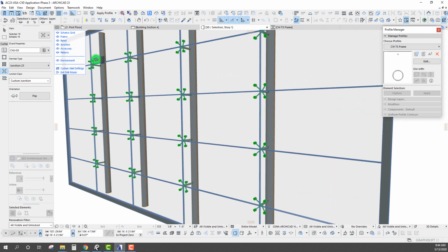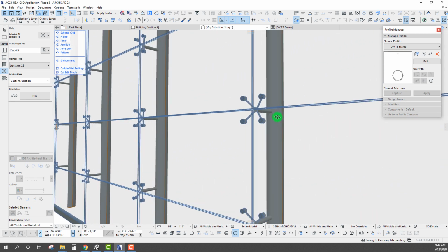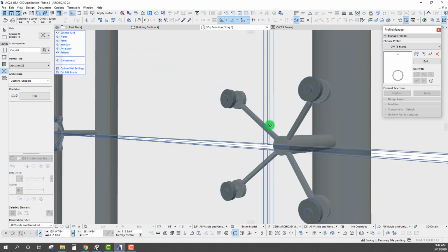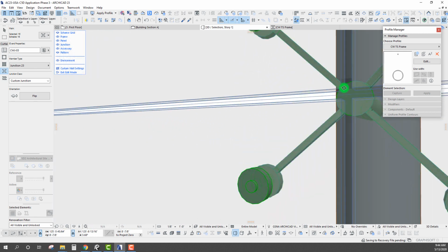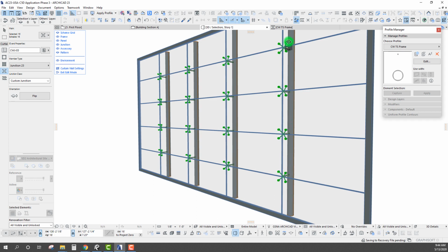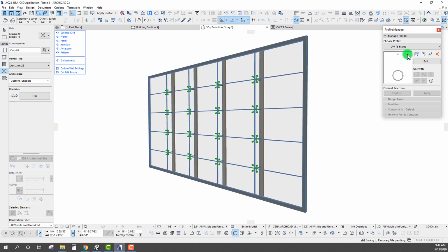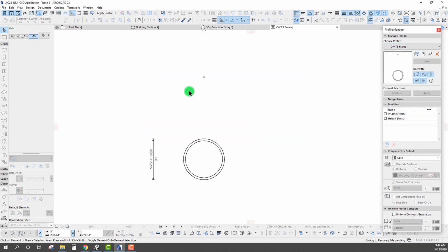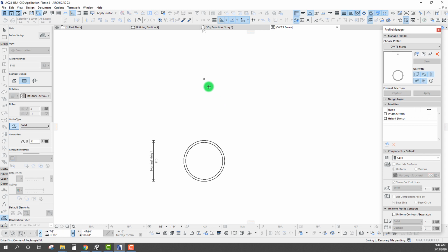And okay, so I'd say to add just a little bit more realism to this, instead of having these actual gaps here, let's create a little bit of a sealant strip there. And we can actually do that directly from within our curtain wall tube steel frame profile. So we'll go in here, and once again we have a 1 inch thick glass panel.